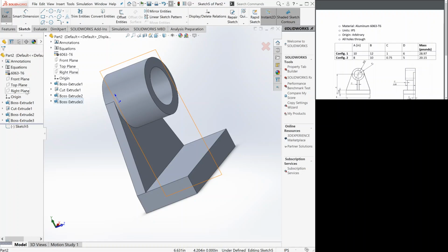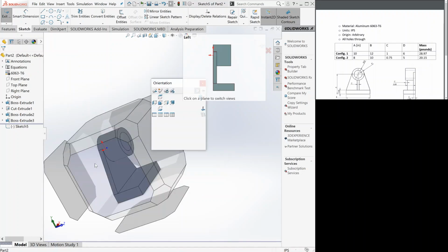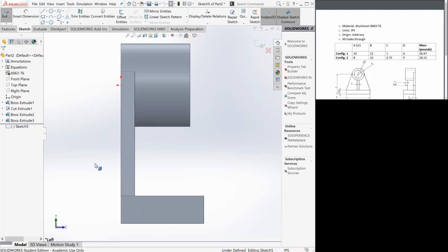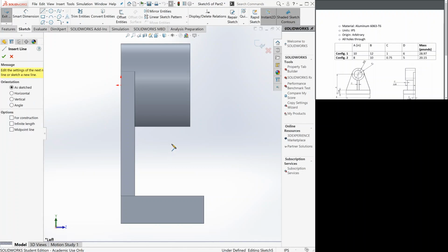Make sure you're able to see that right plane perfectly. Now grab your line tool and make a line that is coincident. You can tell it's coincident because right next to my little tool, there's a highlighted yellow figure with 3 lines and a green dot.